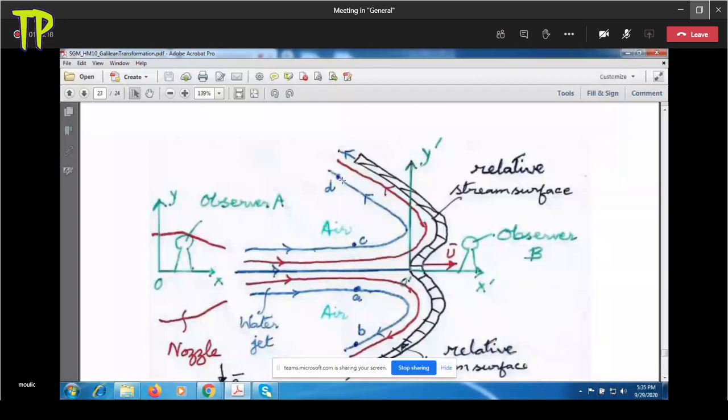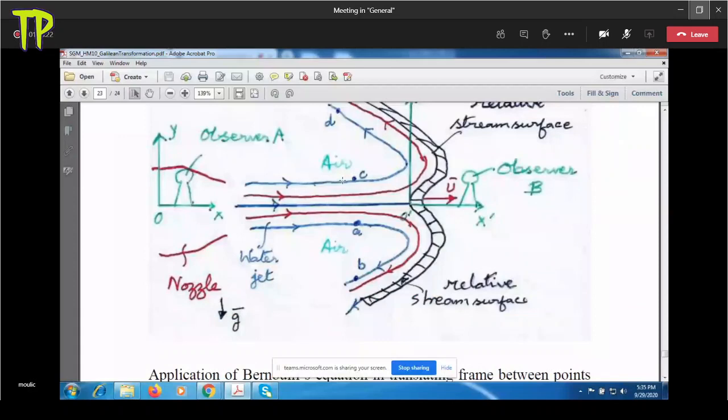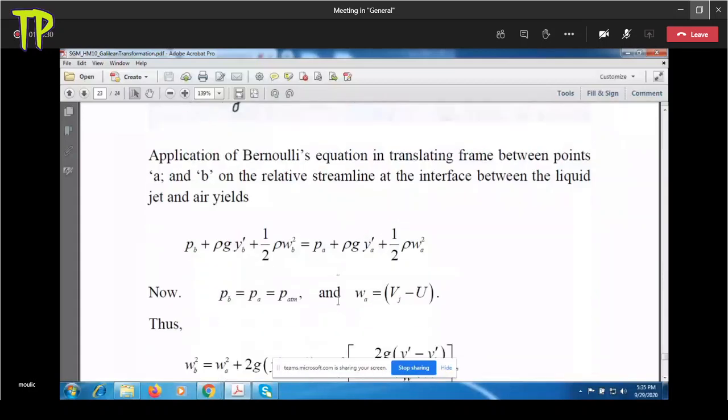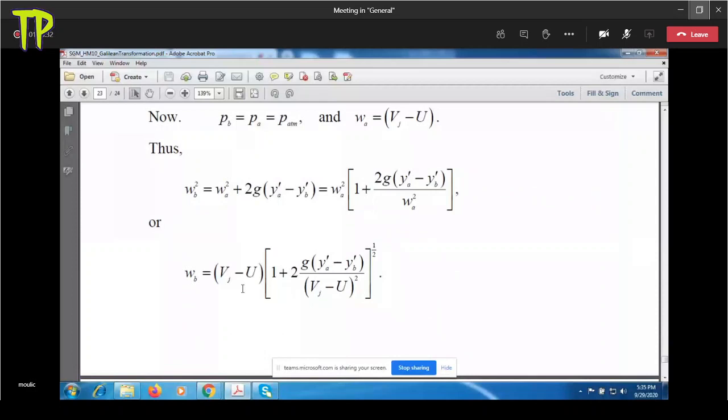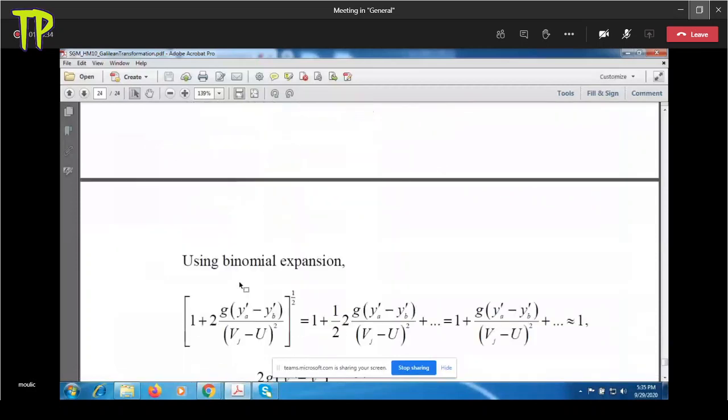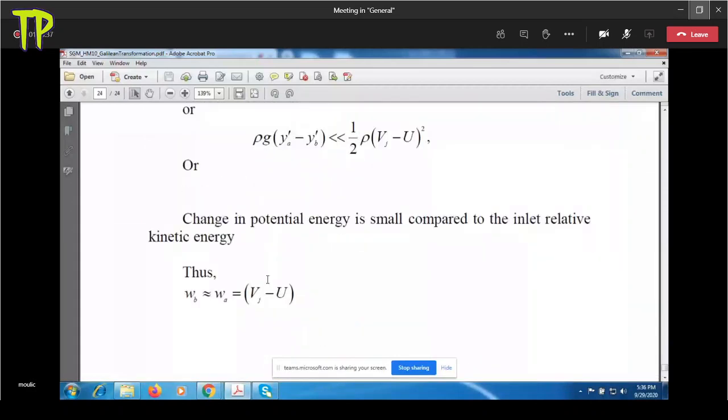The magnitude of the relative velocity. But the absolute velocity will actually decrease. Unless, of course, u is 0. If u is 0, the vane is not moving, then the absolute velocity remains unchanged, and you're not extracting any energy from the fluid.